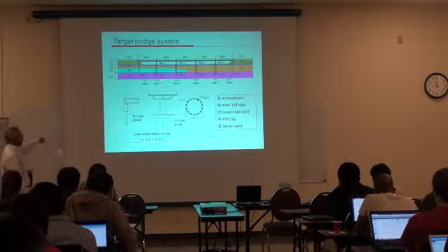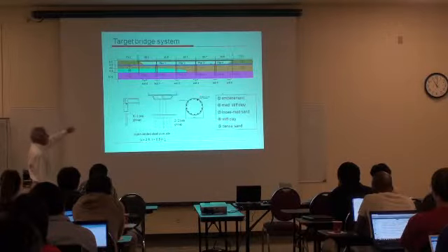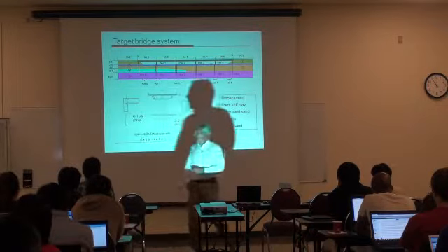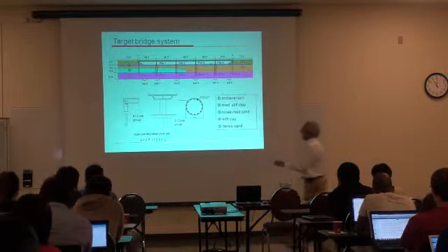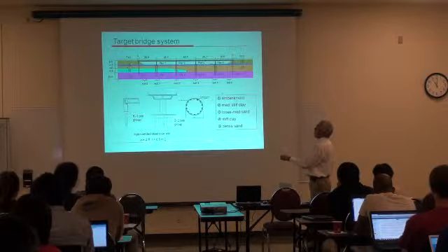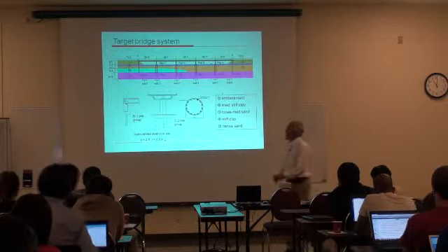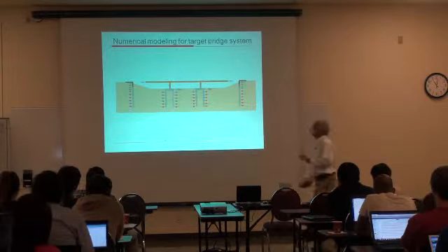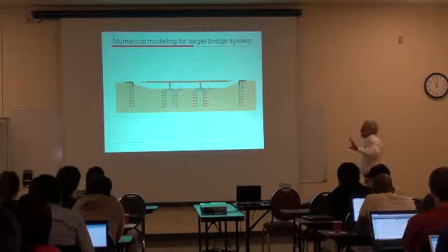Look at the cross-section for the bridge deck. These are the column configurations. This is the pile, the embankment, the abutment configuration, 6 times 1 pile group, 3 times 2 pile groups here. So how to model this? So we said, OK, we are going to start using springs and basic two-dimensional elements.